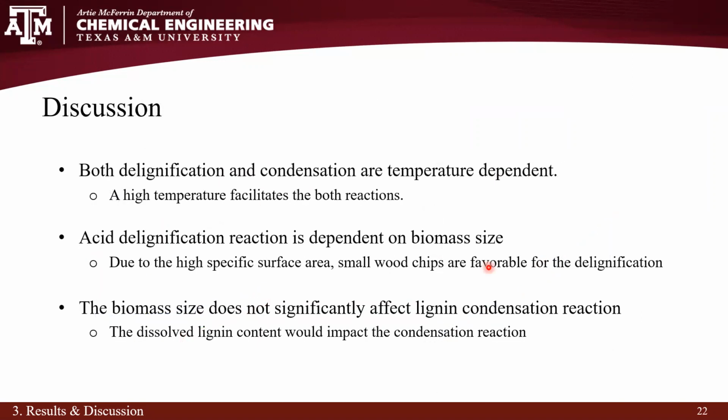So let's sum up the results. First, both delignification and condensation are temperature dependent, in other words, high temperature facilitates both reactions. In addition, acid delignification, the forward direction, is dependent on biomass size, and it is due to the high specific surface area of smaller chips. The small chips are more favorable for the delignification reaction.